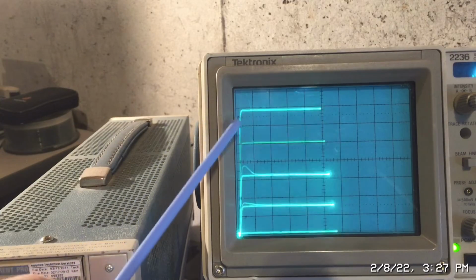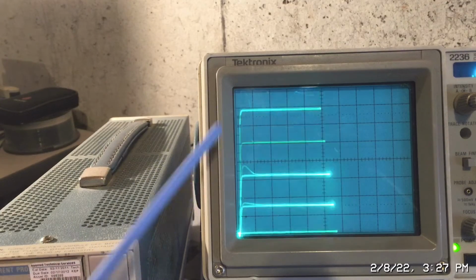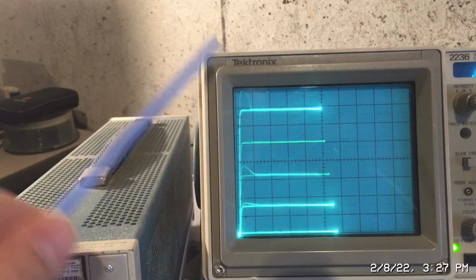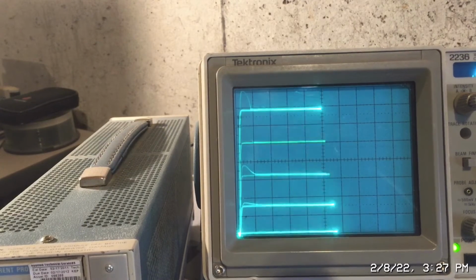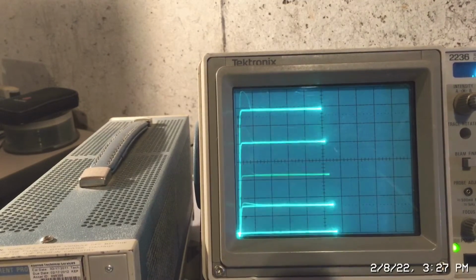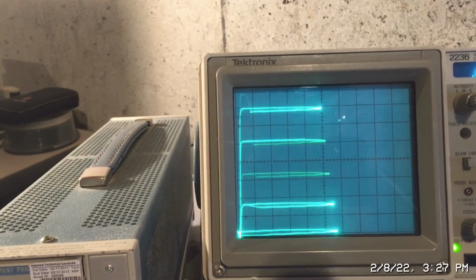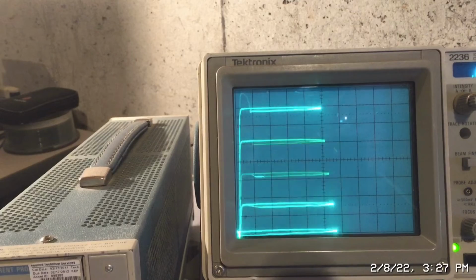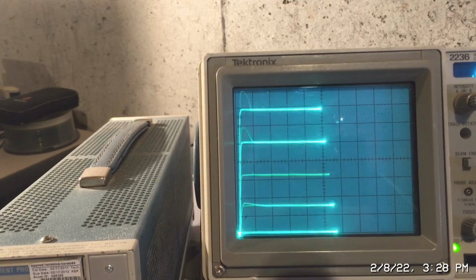Incidentally, this is called looping. Okay, this depends on the amount of capacitance that the transistor has, the input capacitance as well as the output capacitance, and there is a loop adjustment on this particular analyzer. Sometimes it helps, and yeah, that's not bad. We can bring it back together. So that's basically caused by the parasitic capacitance of the transistor.